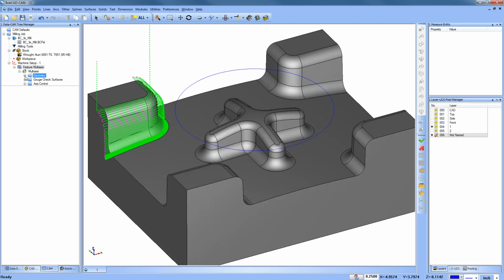Using a morph style, you can do compound curves, you can do all kinds of stuff. Another thing that's really important to understand is these toolpaths support undercutting. All of these toolpaths support undercutting. So if you're using a ball mill or a lollipop mill or a dovetail mill or a T cutter, if you're using any of those types of tools, the toolpath will have access to the undersides, the tops of the balls, etc. Any type of extension to trim in 3D Pro.